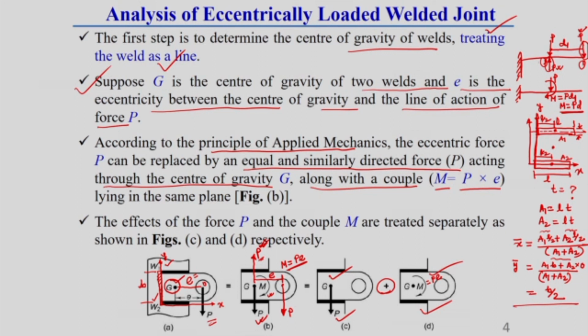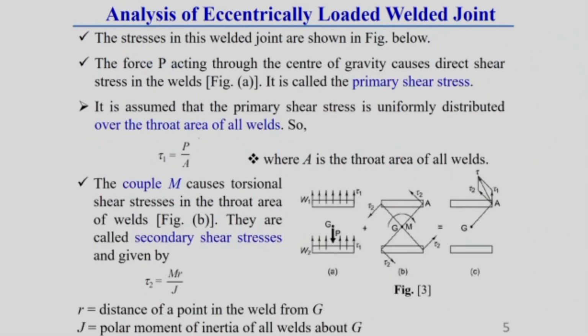The effect of this force P and the couple we will now treat separately, which you can see in figures C and D. Depending upon this externally applied load P at G and this couple M, it will create some shear stress. How this shear stress comes into the picture, I will show in the next slide. You see, there is a direct force passing through G, which I am showing in figure A.